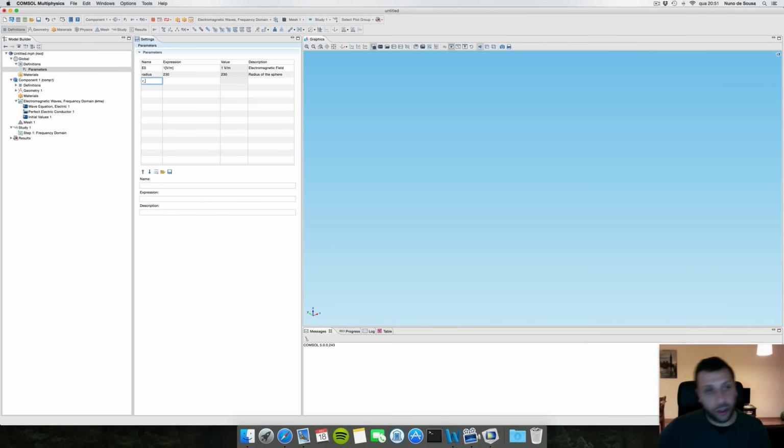And like you probably should know, we should have the perfectly matched layers and these perfectly matched layers must have a radius. So we're gonna define the radius of the PML, and it's gonna be something like 10 times the value of the radius. Okay? And we're gonna say that is the radius of the PML. Also, the thickness of the PML, I suppose, like I already told you, that you know what is the meaning of perfectly matched layers, what is behind this.